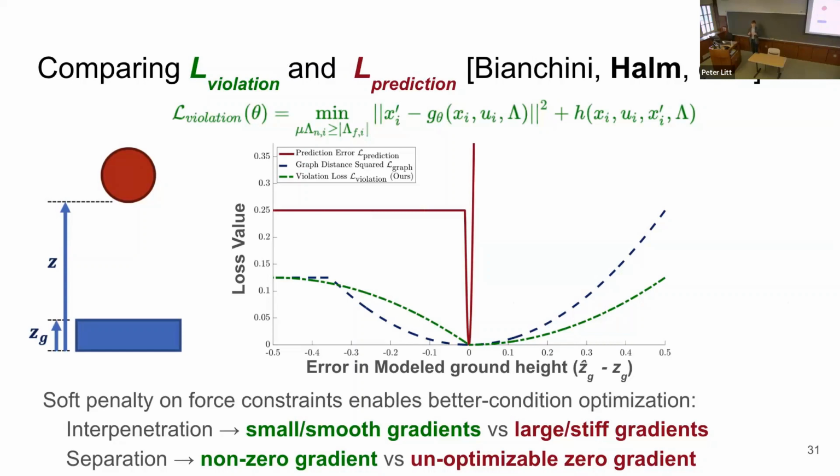So that's maybe a way of thinking about reconstructing, doing state estimation and learning at the same time from limited observations. Another way of thinking about it is, again, just using the physical structure. Instead of thinking about learning from states as a whole and inferring these contact forces, you could also fuse that with contact force sensors. We often have 6-axis force torque sensors in end effectors that we could directly use to capture what forces an object experiences. And then through methods like that, you might be able to completely decouple the dynamics of a manipulator from just one moving object that it's trying to manipulate and set up a much simpler training process.